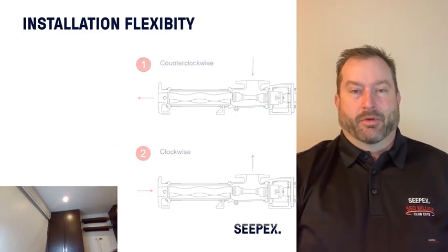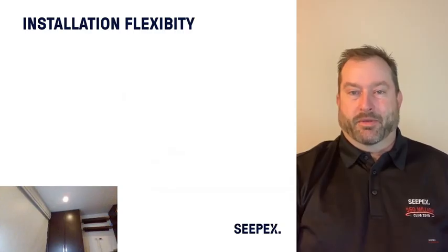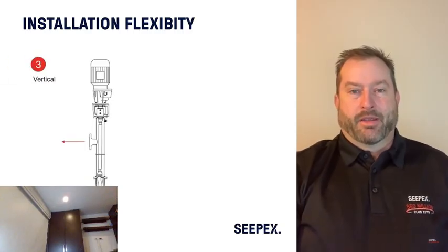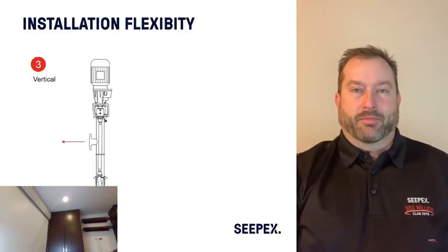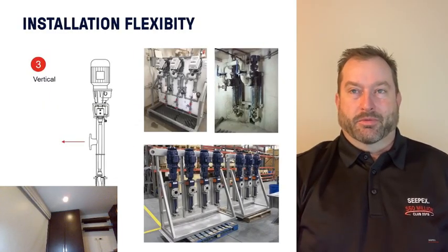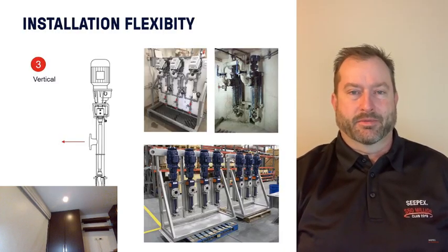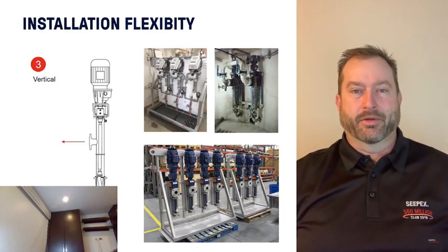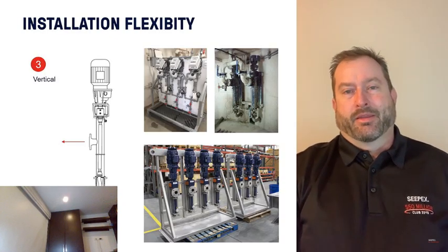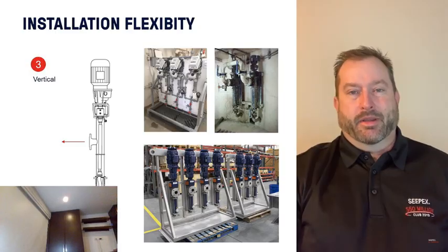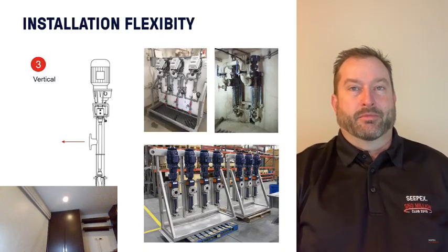It's pretty common for PC pump manufacturers to mount these pumps horizontally as a standard. But you also see a lot of these pumps mounted in the vertical configuration as well. Most pumps, the suction casing, since it comes in, the suction flange is at a 90-degree angle to the pump. That can typically be rotated at 90-degree increments, so that position can be changed as well.